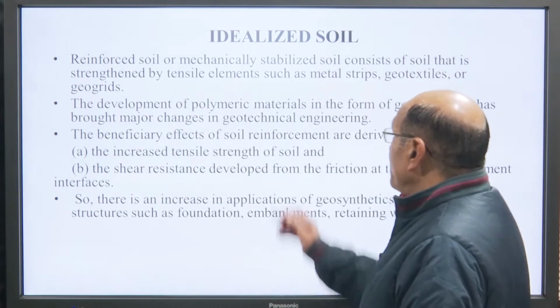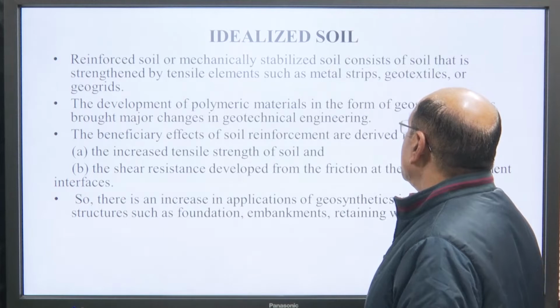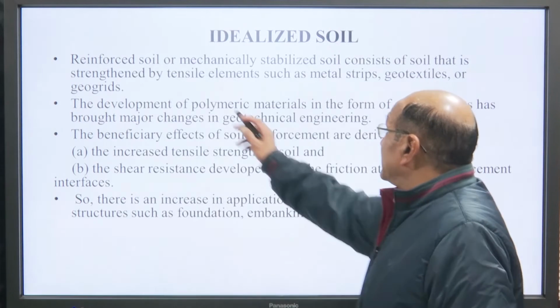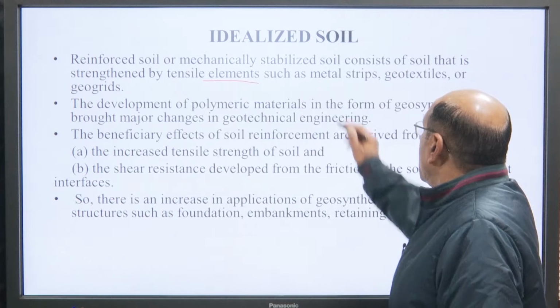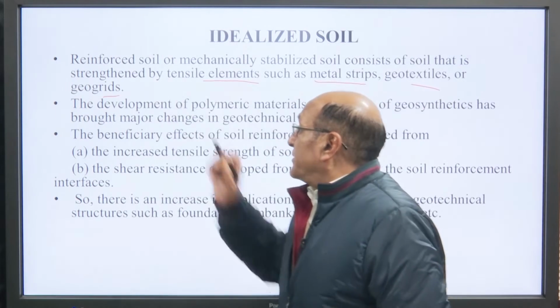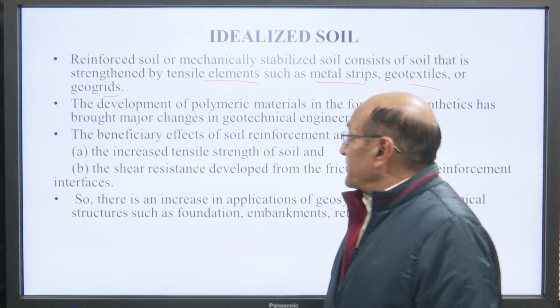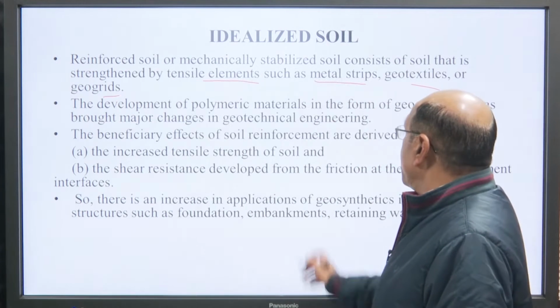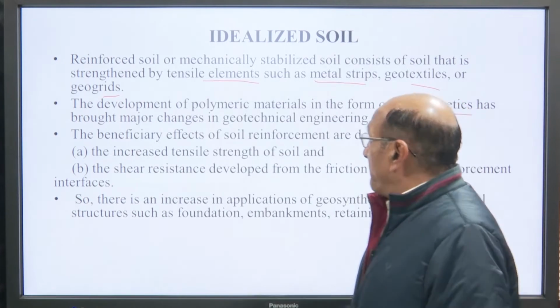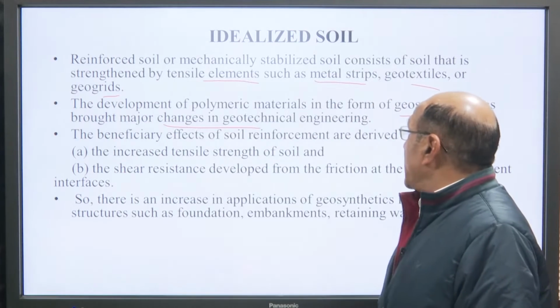Now, reinforced soil or mechanically stabilized soil consists of soil that is strengthened by tensile elements such as metal strips, geotextile or geogrid. The development of polymeric materials in the form of geosynthetics has brought a major change in geotechnical engineering.